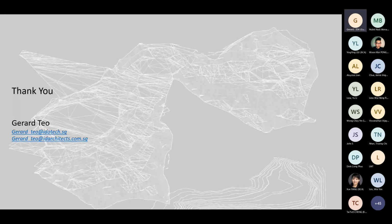The concern would be the amount of information you could extract from your Excel and your CAD file. For example, does your CAD file have everything separated properly into layers? Within those layers, are the lines all clean, do things that are supposed to connect actually connect, and are closed loops really closed? As long as your data source is rich enough, it's definitely a potential candidate for automation.